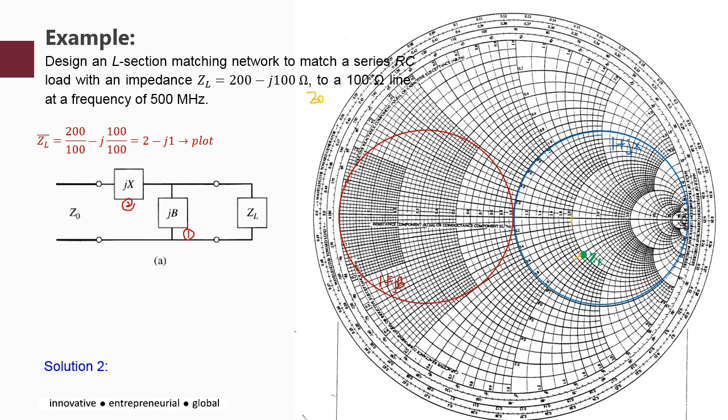Right, in order to have the admittance, as discussed earlier, the admittance is basically the translation or the opposite of your ZL. So you draw your SWR circle and get your admittance YL. Okay, so your YL in this case is 0.38 plus j0.2. Next you need to match the YL position to the 1 plus jb circle.